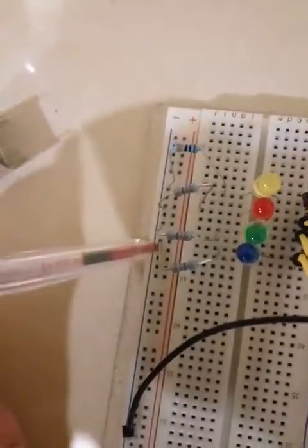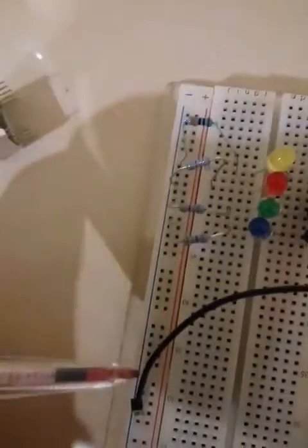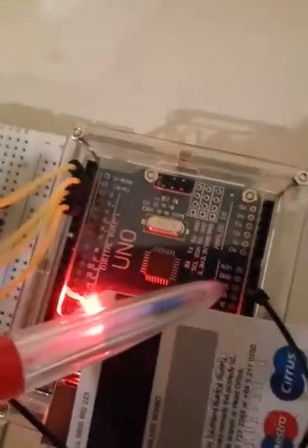Okay, now your challenge is to make a series of LEDs light up one after the other. You'll see here I've got 4 LEDs, each with their protective resistor. I've got the resistor on the negative rail here with a black cable going into the ground, GND,